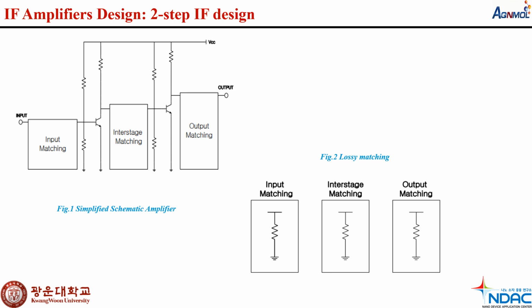What is the interstage matching? A frequency dependent mismatch is introduced to improve the stability. For example, the traditional K factor might not be sufficient for assessing stability here. And secondly, in the ideal scenario, an unconditionally stable transistor would have 50 ohm matched input or output for maximum power transfer.